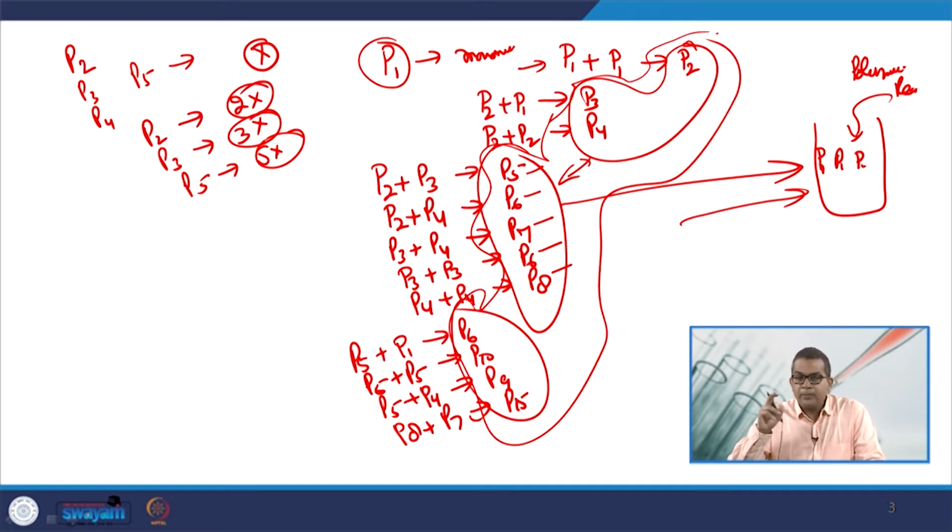If you keep on running this polymerization process for a longer duration, then there may be a chance that higher molecular weight chains get formed. In that case, the molecular mass of that polymer would be on the higher side. It may create the problem of processability, as I discussed in the previous slide.